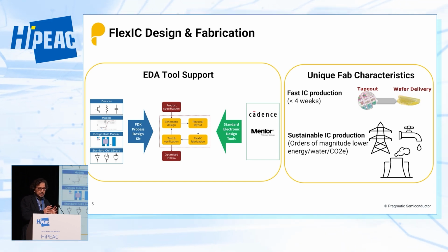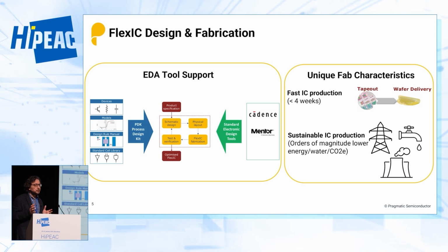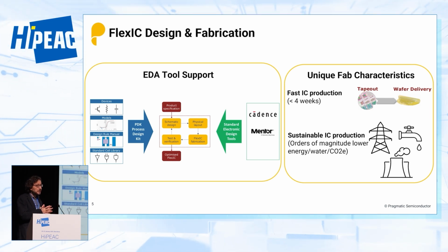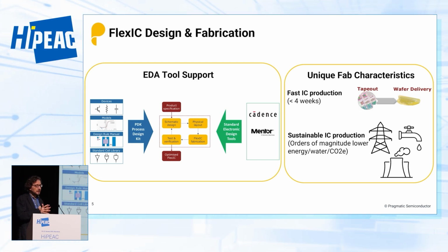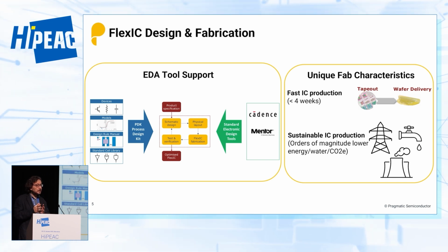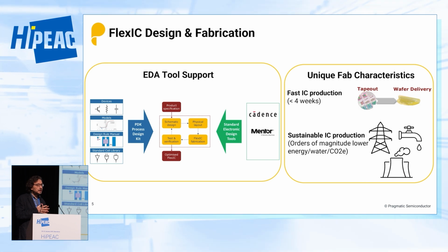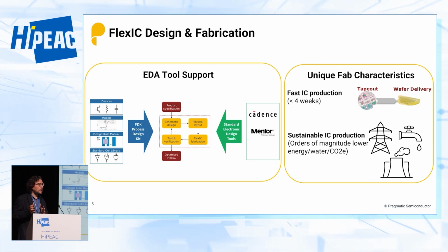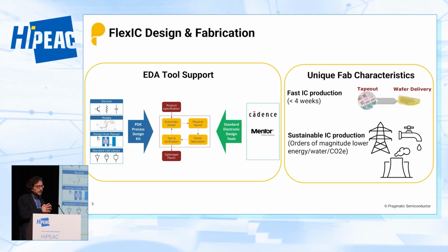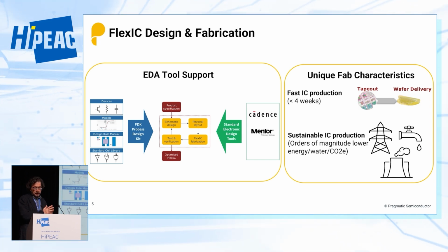So let's look at the design and fabrication. I get this question a lot: do I need to do anything special to use your technology? No. We provide a PDK and a standard cell library, and they are enough to be integrated into commercial EDA tools, so you can design your chips as if you are designing for other foundries. From that perspective, it's no different. If you're designing a silicon chip, you can also design a flexible chip in the same way.